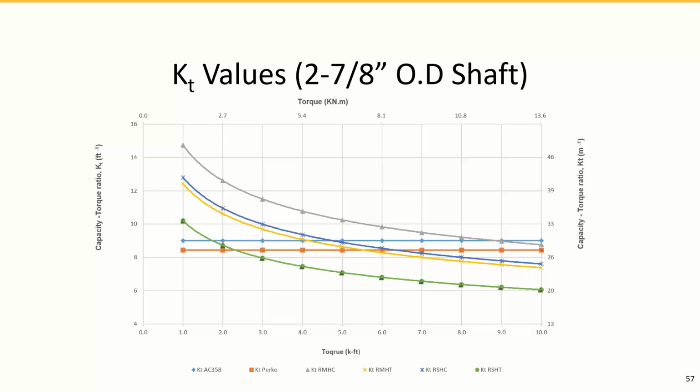Whereas if you test it in tension, remember you're pulling on the top soil, which is disturbed. We say that we shape these helices, and the way we install it and all this, we minimize the disturbance of the soil, but we didn't say we completely omit it.